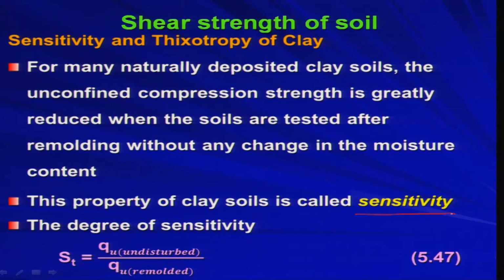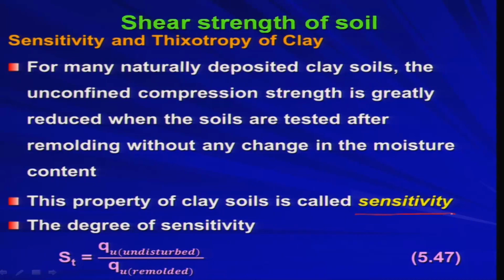If I say the sensitivity is 2, or the sensitivity is 4, then you should know that whatever I get from the laboratory unconfined compression strength test may not be the same as what is actually lying in the field. So, this sensitivity talks about that kind of variation.